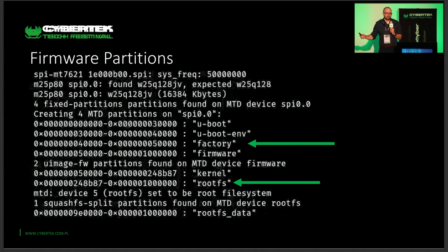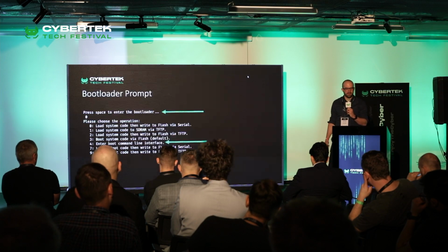And most hardware hackers or IoT hackers would go for the rootfs file system, right? Because that's where the goodies are. But not us, we are in OT, and in OT everything is different, so we go for the factory partition.